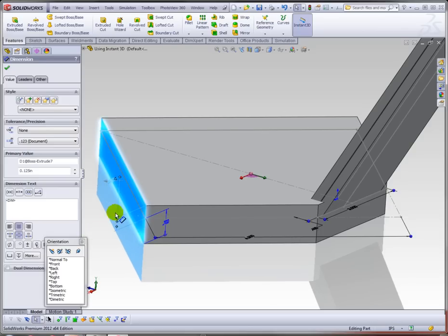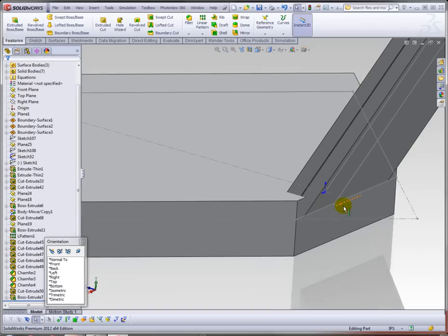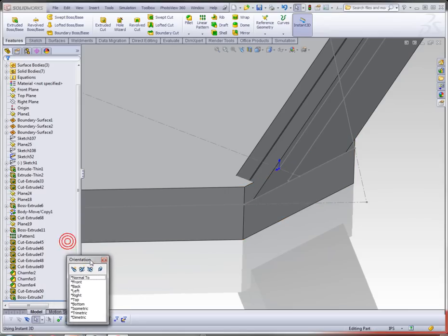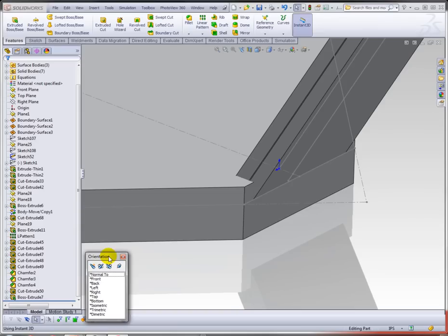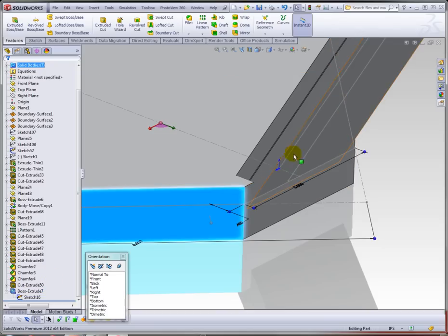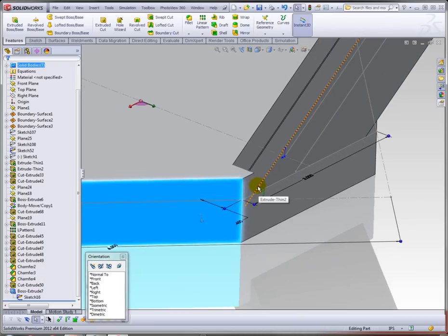Now, that's great in one aspect of Instant 3D, that it helps me be very quick when I'm doing modeling and also modifying my model. But it's also something that I find is indispensable when actually making adjustments, because it's the only way to do it. In the case of this area here, I want this edge actually to grow out to this edge here, and it's really hard to do that in Sketch.